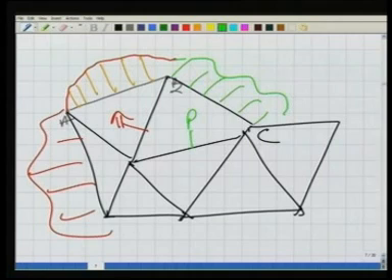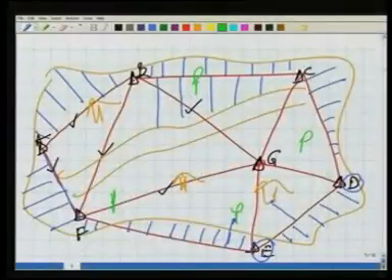So what we are seeing here is again the concept of working from whole to part. For our entire area, we did not start taking measurements from a single offset, a single detail. Rather, we started taking the observations in a big way. First we made a network of triangles. This network of triangles is the skeleton of the area.